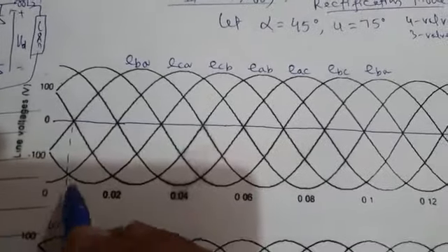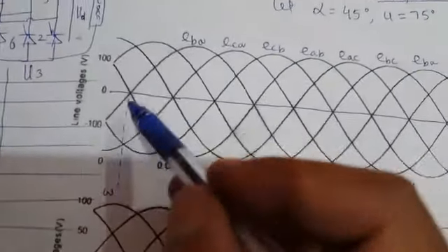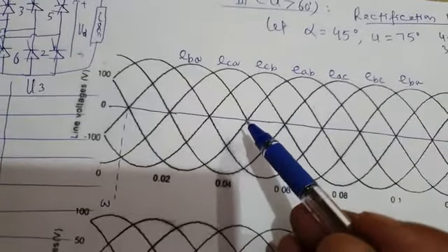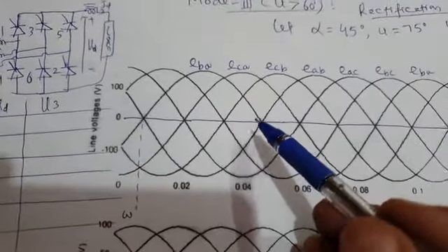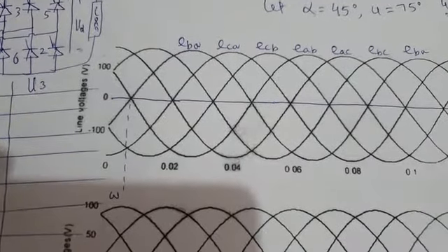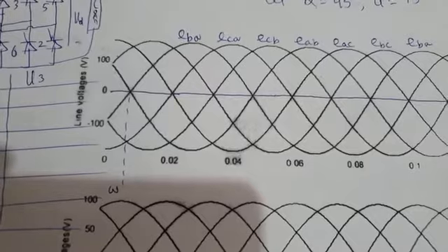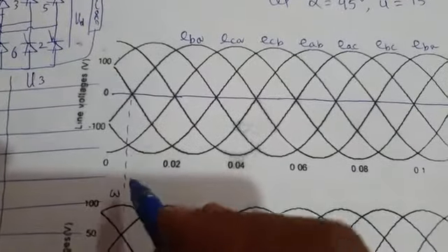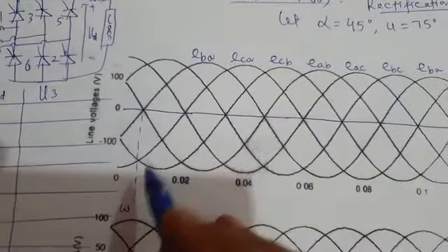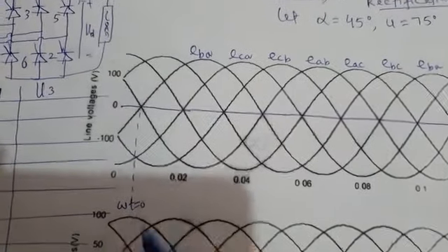Okay, so this is the commutation voltage of valve 3, the original commutation voltage, which again we take as a reference, whereas the actual commutation voltage is minus 1.5 EA for valve 3, but we can take EBA also as a reference. So this is the zero crossing of EBA, so this is omega t equal to 0.